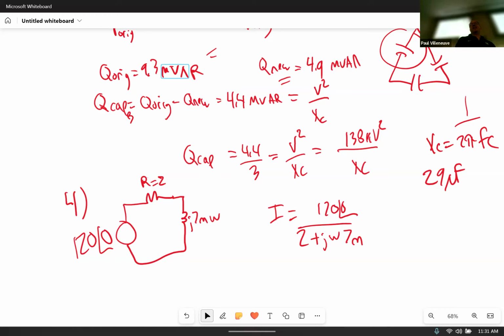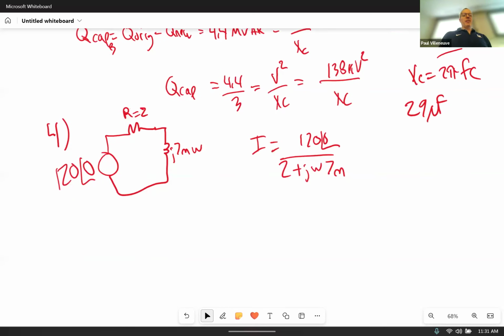Then you'd have to go back and either do time domain analysis, or you could do Laplace domain analysis. But in AC circuits, the reason why we multiply that is because if I wanted to solve for the current in an RL circuit, L di/dt is the voltage, right?